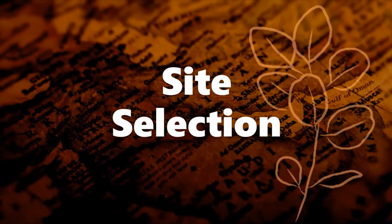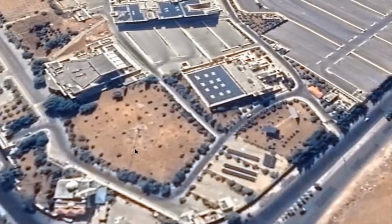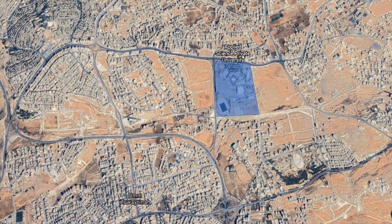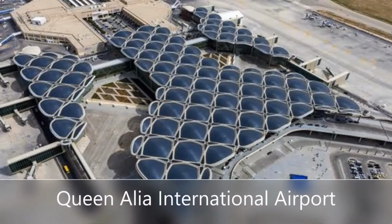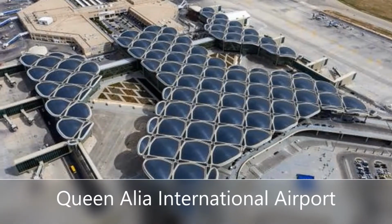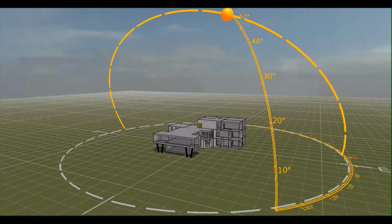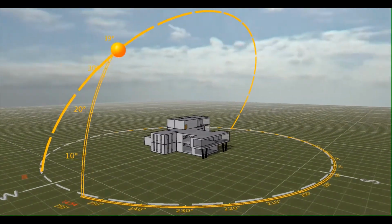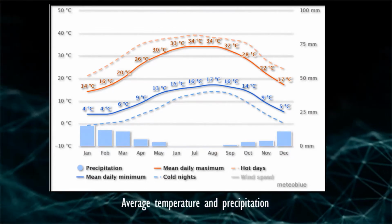Site selection. Our project is located in Amman, Jordan, within the campus of Applied Science Private University. The site is located near a main highway and within an urban area that is easily accessible. The weather profile used is Queen Alia International Airport, which was the nearest available location to our site. Sunrise and sunset direction is northeast to northwest during summer and southeast to southwest in winter. Lowest and highest mean temperature is from 4 to 34 degrees centigrade.